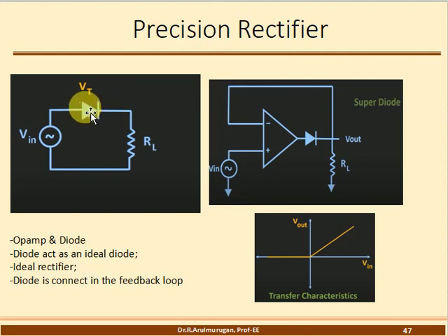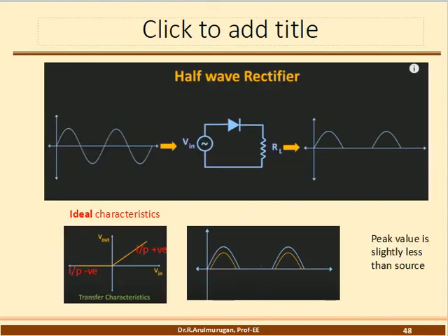If you want to reverse that, you connect the diode the opposite way, so only the negative half cycle conducts. Coming to the point as per the given circuit: the phase with respect to neutral, the positive half cycle is conducted. During the negative half cycle, the bottom is the phase with respect to neutral, the diode acts as an open switch, so the current does not flow during the negative half cycle. So this is the half wave rectifier we discussed: the positive half cycle only is conducted, the negative half cycle is 0.